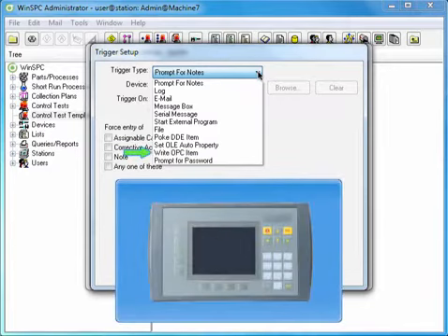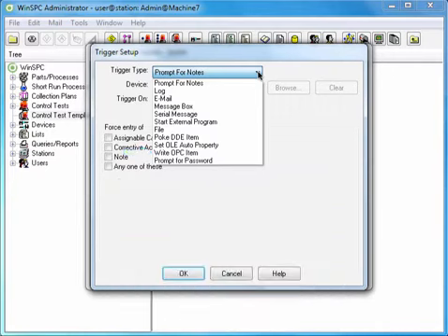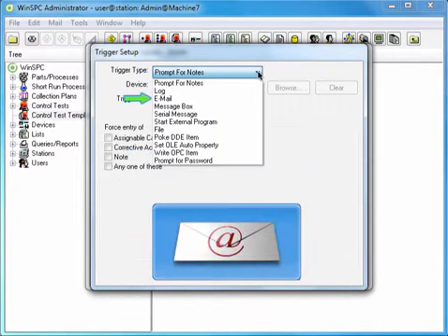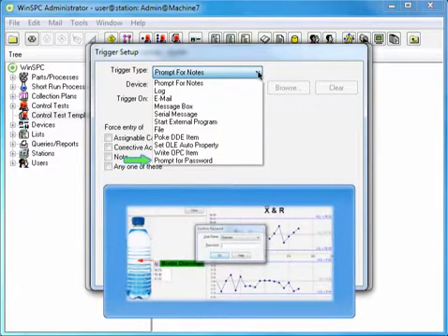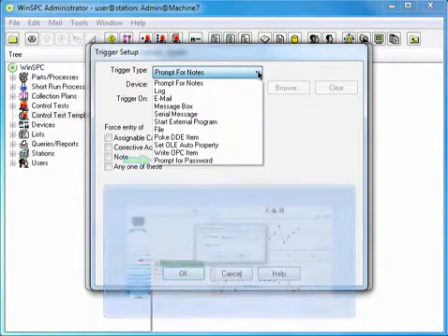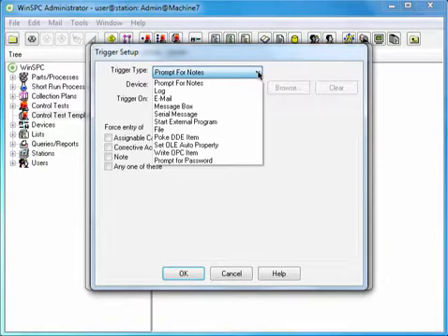The write OPC item trigger, for example, can automatically send a set point or calculated value to a PLC that uses OPC technology, enabling the PLC to self-correct a setting, such as temperature. You can email supervisors or other personnel when a test is violated. You can interrupt data collection and prompt for a supervisory password, or trigger a variety of other actions. If you would like an explanation of a trigger in this list, mouse over that trigger now. Otherwise, select Message Box.